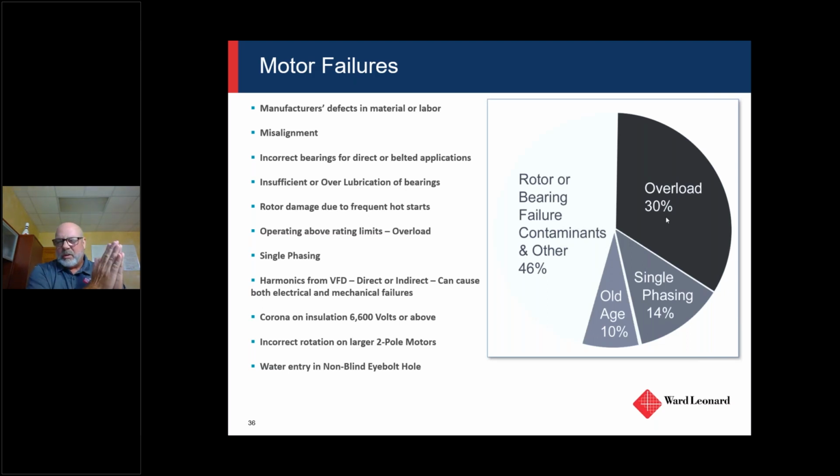Those cheaper materials will delaminate over time, and then it'll fail. So Nomex gives you the ability to stretch the life of the motor out, right? But over time they just get old and embrittled, just like I said. If motors are applied correctly and maintained correctly, you could easily have a winding that lasts 40 years. But you will have to maintain it mechanically, because you just won't get 40 years out of your bearings for sure.